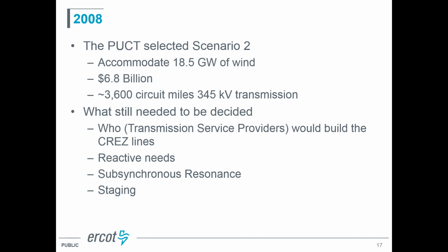As part of the design, we also incorporated series capacitors onto the system, and we really found that was an economic choice to make. And with series capacitors, you have this resonance phenomena where you can have resonance between the capacitors and generators, and so there were additional studies that needed to be done to make sure that we weren't causing any sort of reliability issues by introducing the series capacitors.